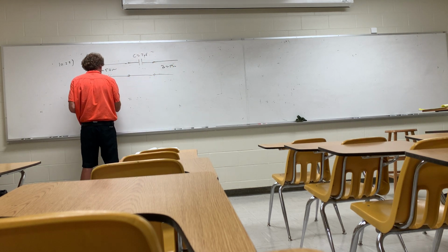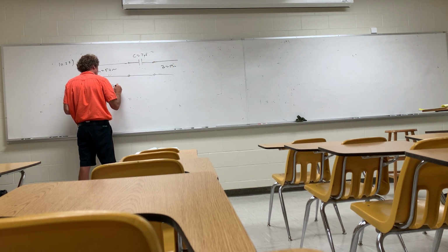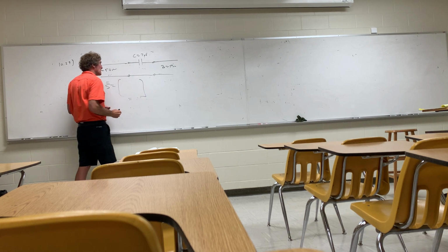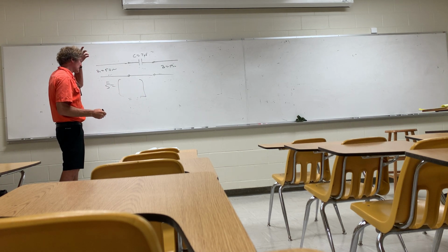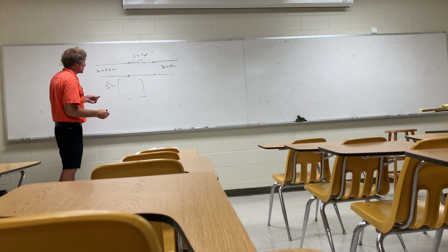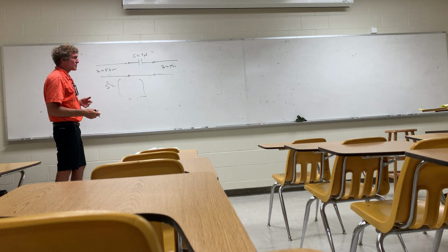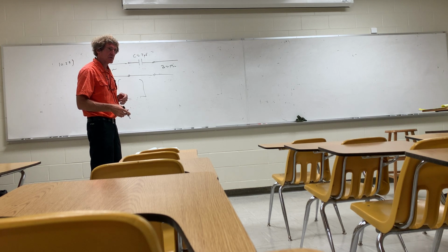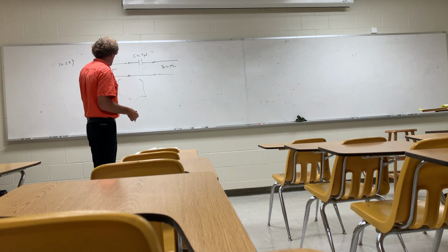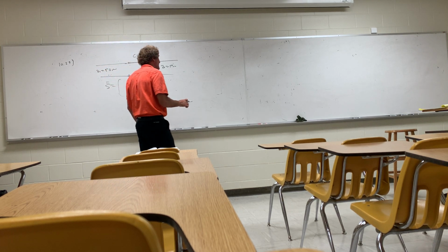Now he wants, first I want at least, the S parameter matrix for this. That's the first thing, so I have to get S11, S22, S21, S12 for that. And then he wants the return loss and insertion loss. We'll get both of those in a second. How do I get the S parameters? Start out by saying, how do I get S11?